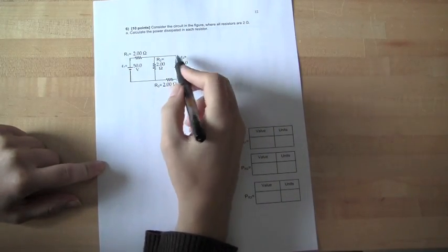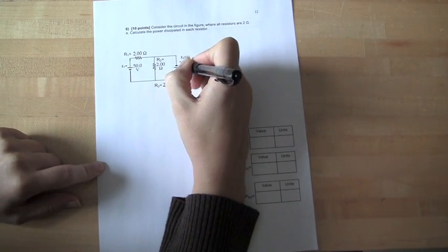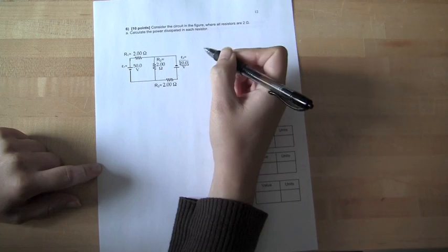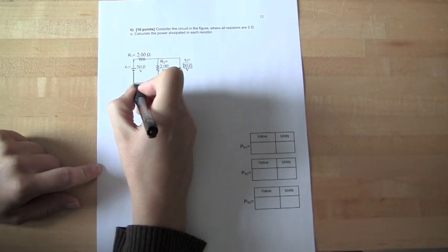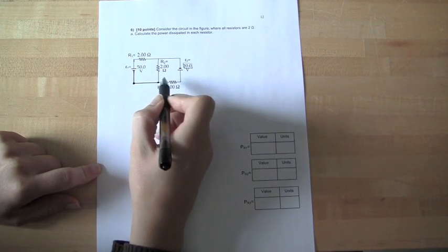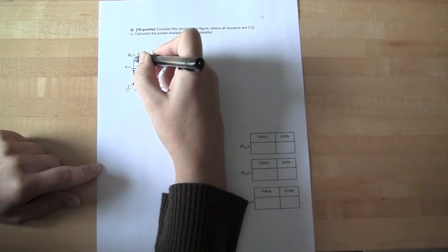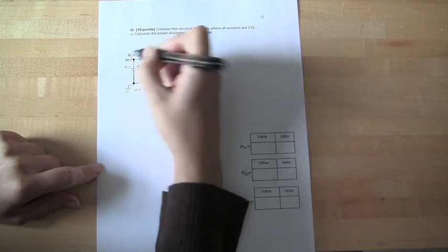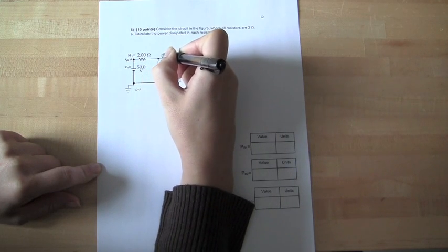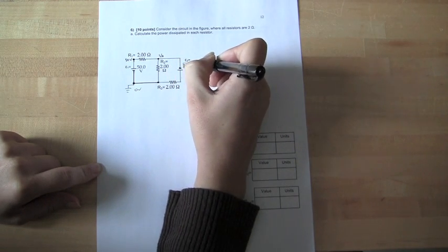Okay, so the way to deal with multiple batteries is still just that you know that each battery causes a voltage difference between either side of whatever the battery voltage is. So for this circuit, on this side of this battery, all the points connected to here are at the same voltage, and we can call that ground, 0 volts. Which means that on the other side of this battery, this point is at 50 volts. If we go through this resistor to this point, you don't know what this is anymore, so we'll call this some potential VA. And this side of this battery is also at VA.